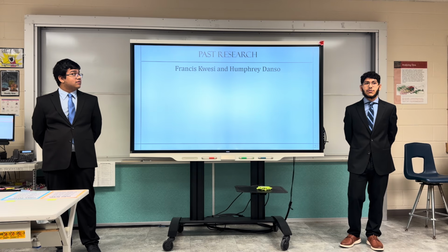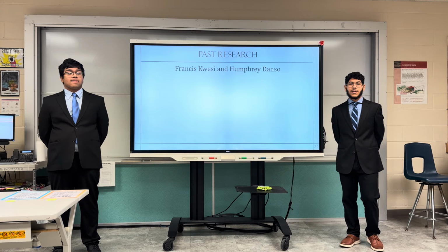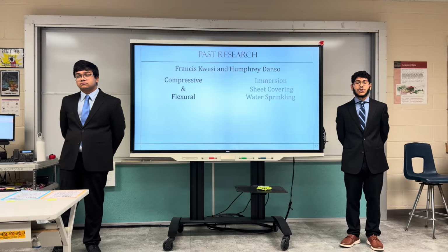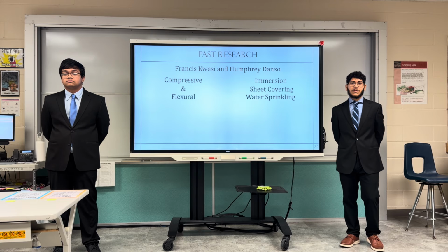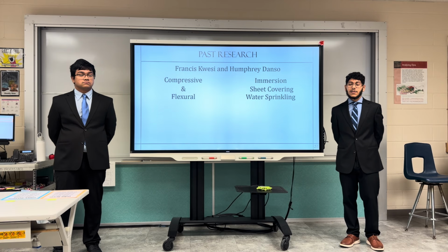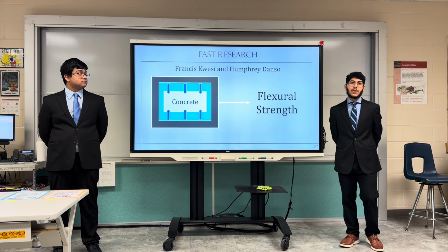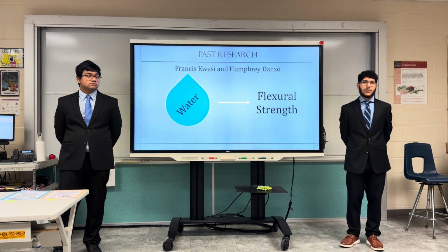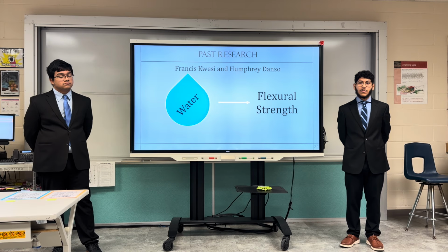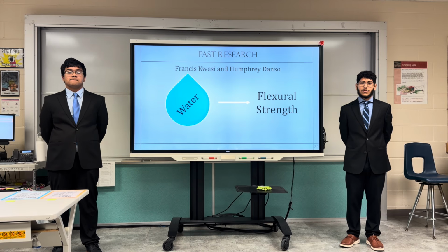And past research also agrees with us. Past research by Francis Quessy and Humphrey Daniso, who investigated the compressive and flexural strength of concrete and the effect which curing had on this, especially multiple different types of curing, such as immersion cured, sheet covering, and water sprinkling, found that curing does lead to an increase in flexural strength. And not only that, but the curing which provides the greatest level of hydration had the biggest increase in flexural strength, as there was more water available to continue those chemical reactions, which developed the internal microstructure, leading to more stress resistance, more force withstood, and thus a greater flexural strength.